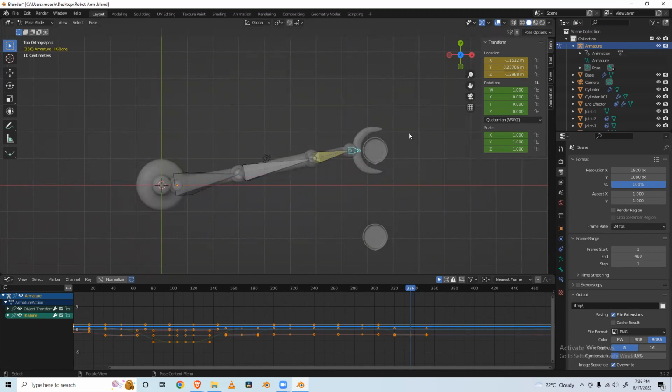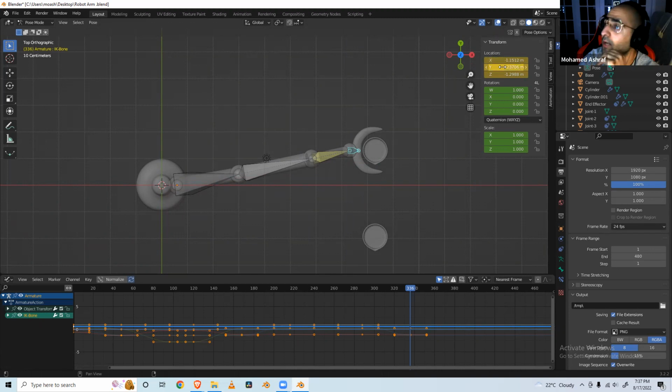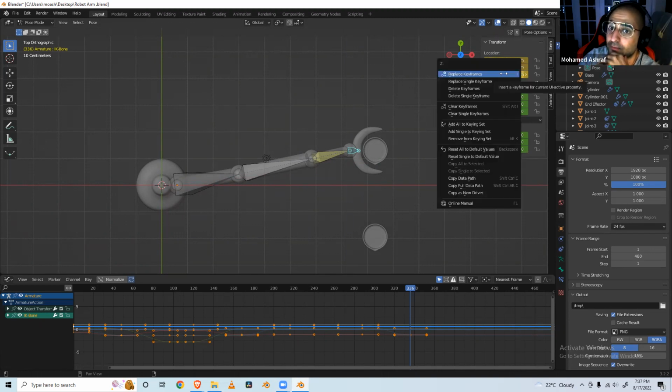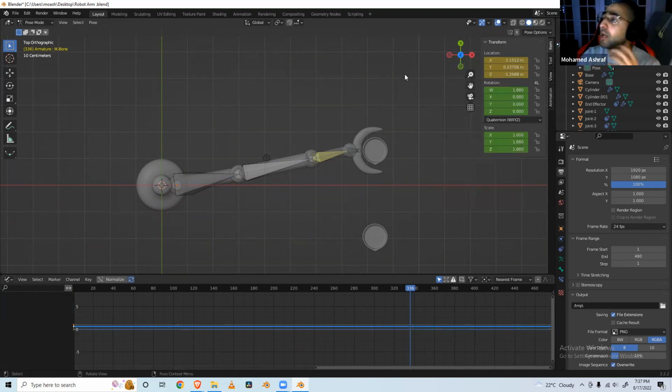And what are you pressing to do that, insert and mark those positions? Oh, the keyframe? Yeah. Oh, that's a great question. So I just go on the location and right click and insert the keyframe. You can also press I, which makes things much easier. In general, shortcuts in Blender make things much easier in life. So I will insert the keyframe. If you mistakenly insert a keyframe, you can hold Alt and press I, and that will enable you to remove the keyframe.